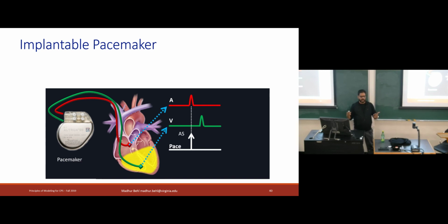So in another situation, when the SA node, it knows that after some delay, and this parameter is set by the cardiologist or the person who is calibrating the pacemaker for the patient, it knows that for this patient, the bradycardia is that the SA node is not firing at 1 second, it's firing every 3 seconds. So if the pacemaker detects that, well, I expected the SA node to trigger a beat to maintain a normal sinus rhythm and it did not, then I'm going to artificially pace.